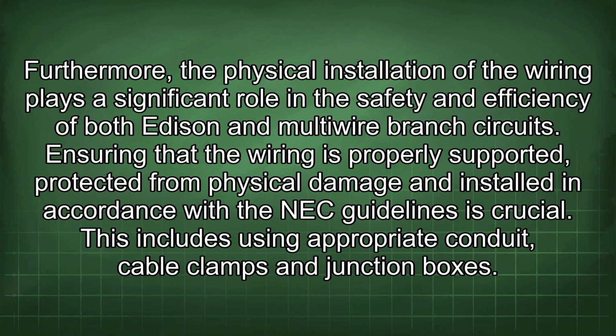Furthermore, the physical installation of the wiring plays a significant role in the safety and efficiency of both Edison and multiwire branch circuits. Ensuring that the wiring is properly supported, protected from physical damage, and installed in accordance with the NEC guidelines is crucial. This includes using appropriate conduit, cable clamps, and junction boxes.